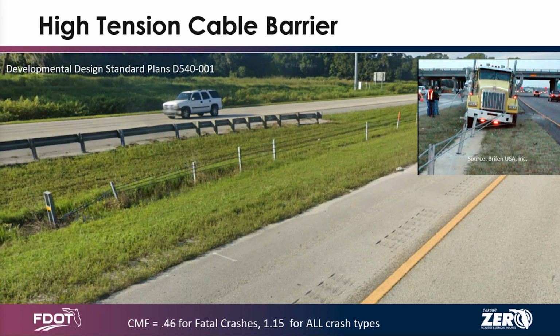So you use cable barrier when you can. If you don't have enough space for cable barrier, then you use guardrail. If you don't have enough space for guardrail, then you use jersey wall. It's following down that process, and what it's saying at that point is that there is no hope that you're going to get yourself out of the mess that you're in. What we're trying to do at this point is just catch you as gently as we can, assuming, I guess, that concrete can catch you gently. But anyways, it is a least worst scenario.